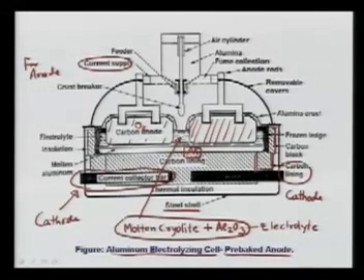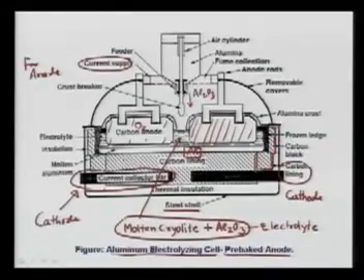But the other thing we need to see is that in the center, this is where you put your constant supply of Al2O3, because that is continuously consumed to form the aluminium. As we put in the Al2O3, it gets dissolved, and partly it will make a little crust on top. You can see the alumina crust, so the whole thing tends to be covered fully.